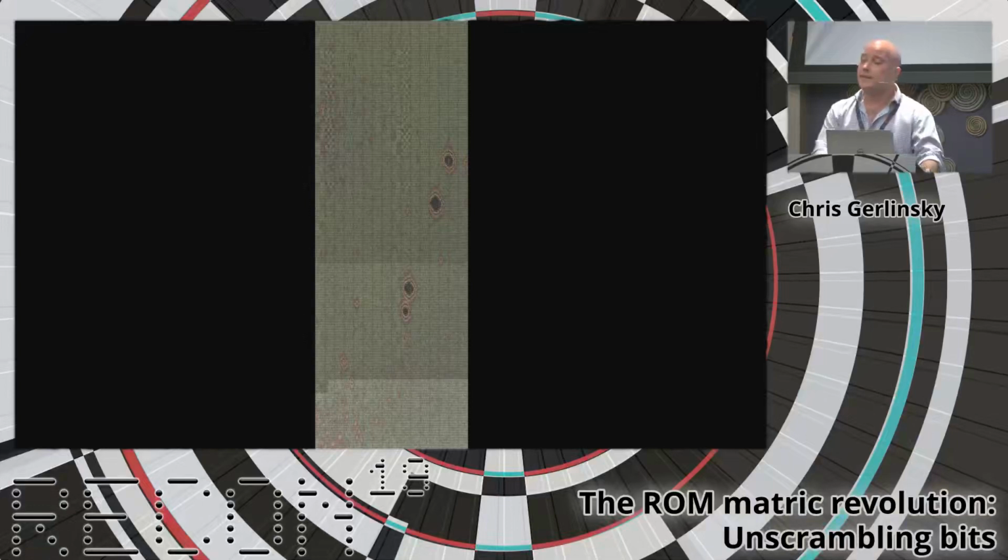There's a few holes in it. That's because I delayered this chip using hydrofluoric acid, and with the wet etching process you don't end up with a totally planar result, so I have some little holes where the acid etched a bit further. In this case, I don't consider it a really big deal. If I need full ROM extraction, I can repeat it on two different chips, and the holes will probably end up in different spots. That works quite well. Another option is to polish a chip instead of using wet etching.